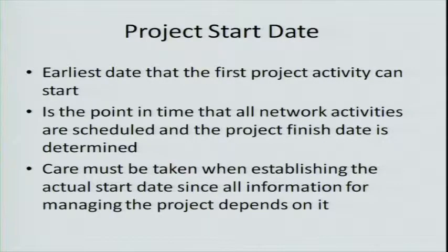And if we have multiple points, if multiple things have to occur before we can start, if activity 3 is based on activity 1 and 2, and activity 3 takes 3 days and activity 4 takes 4 days, but they both start at the same time, what's the earliest activity 3 can start? It can't start till 4 days, because that's the controlling activity. So you have to look at everything that feeds into what we're doing.